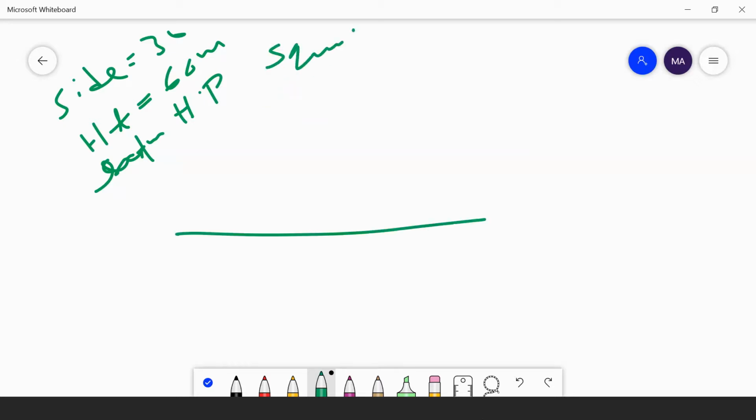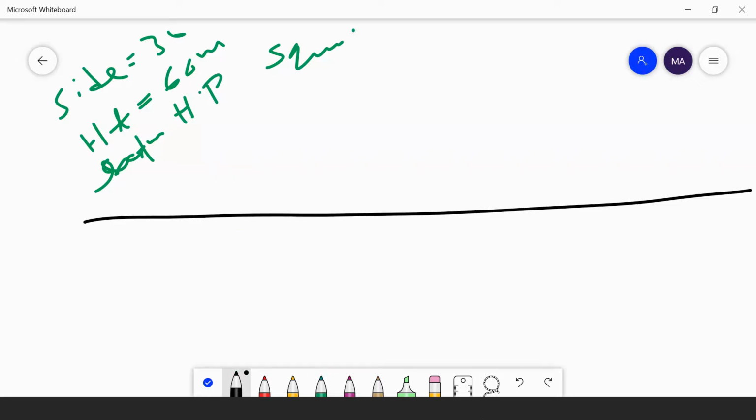First I will take the reference line. I am drawing the square with a 30 mm side. First I will take 30 mm. I have taken 90 degrees. Then I have cut 30 here, then I have cut 30 here. From here I will cut 30, 30. I will get a square. It is ABCD. I am drawing a prism first.